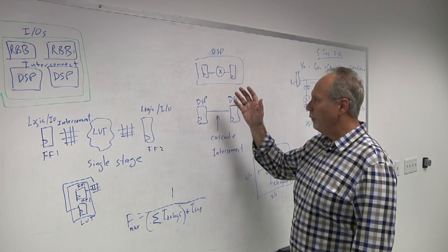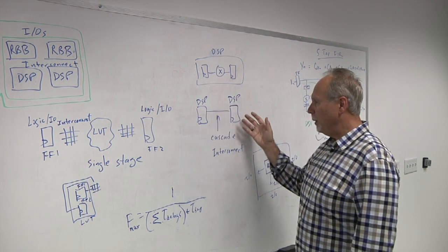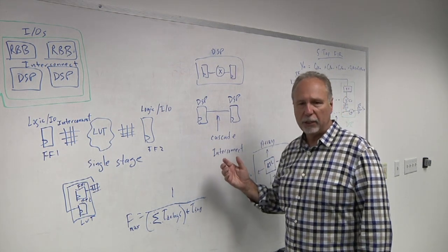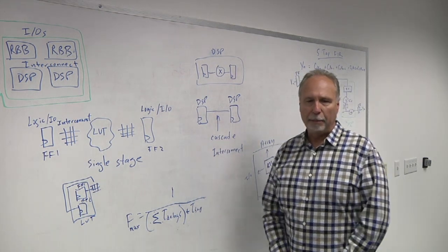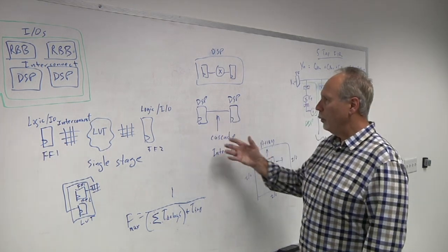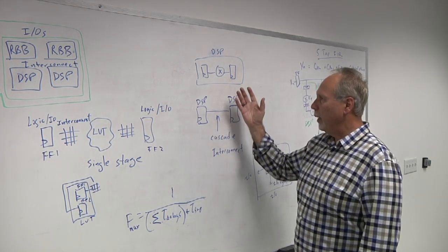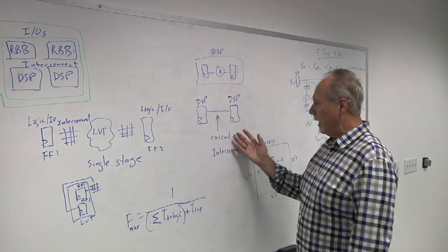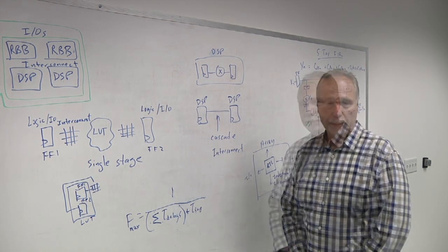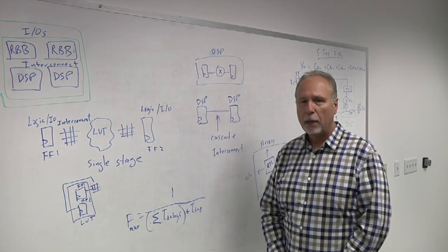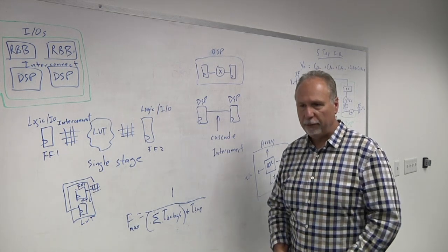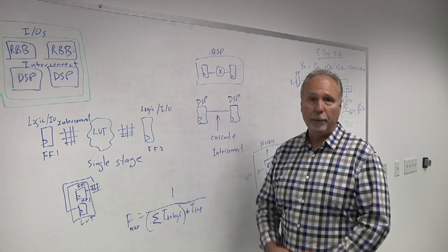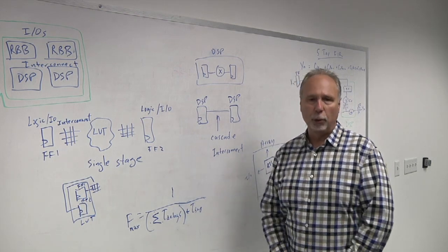The other one is if you're going from one DSP to another DSP through either an interconnect fabric or a cascade mode. For instance, in our performance benchmarking application note, we go through different scenarios and different ways you can improve performance using cascaded mode versus an interconnect, for instance. So basically you have a lot of knobs to play with here, right? Yes, those knobs are done either by Verilog and RTL or by the compiler that the embedded FPGA maps to the technology that it's going to.